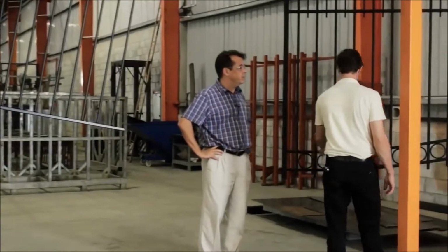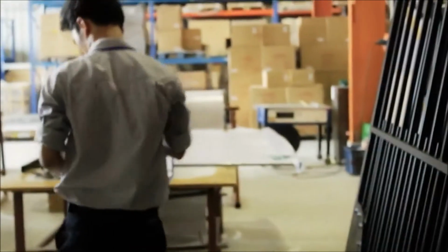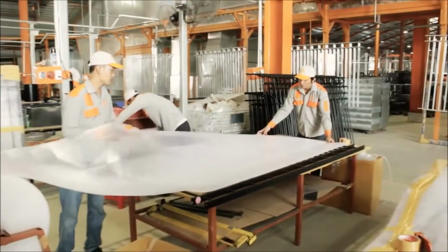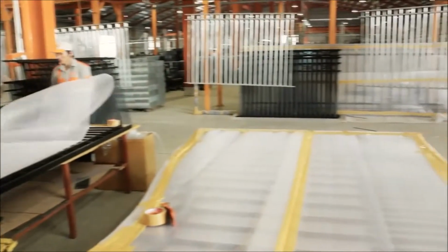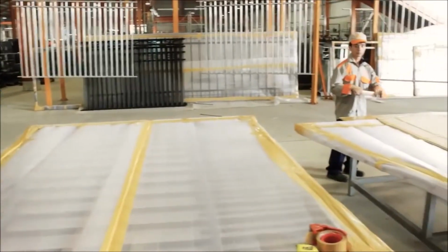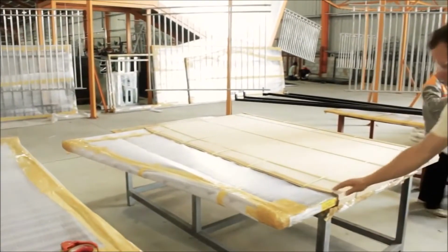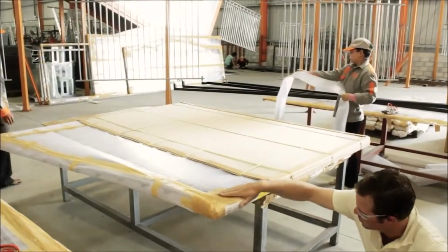So we're nearly to the end of the process. So now the gate's in the hold area prior to packaging. This is where we check and document the thickness of the powder coating. And this makes sure that it is compliant with the certain micron thickness? Yeah, the powder that we use is Tiger Drylac, which is a reputable American manufacturer of powder. We recommend that it should be 60 to 80 microns.